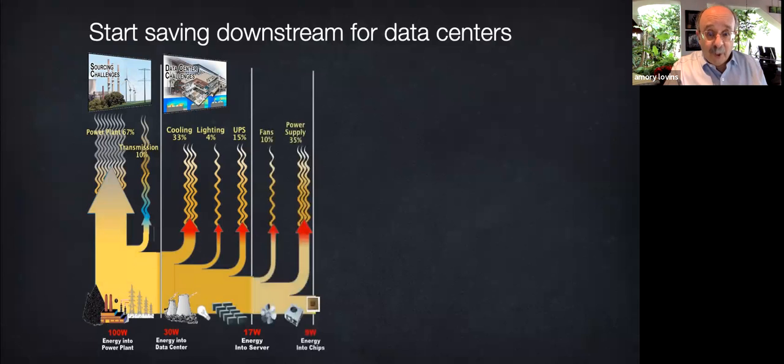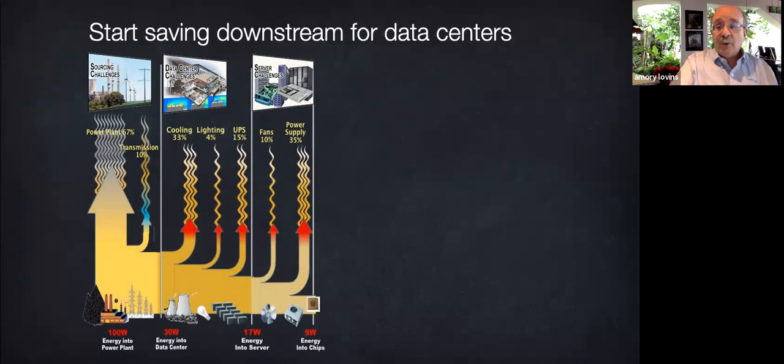Then half the server energy doesn't get to the chips because it's lost in inefficient, usually very underloaded power supplies, and in lots of fans to take that heat that largely shouldn't be there off the motherboard into the room so we can do dumb things with it. By the way, NTT facilities in Japan pioneered DC power supply. That eliminates the power supplies in this diagram.